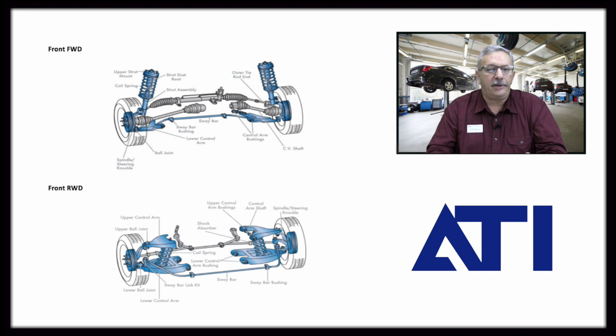And this is traditionally what you see on trucks, even light trucks. It's a smaller box, but it's still a significant weight to it, versus the rack and pinion system, which is lightweight. And it's an aluminum tube, basically, with a steel rod that runs through it, and it's a worm gear that operates it. So that is the difference between the two.